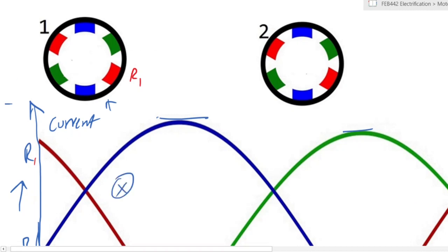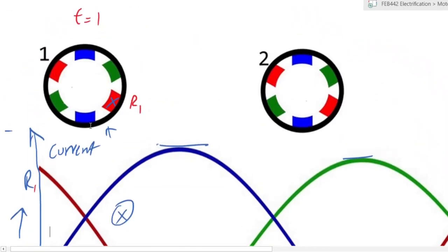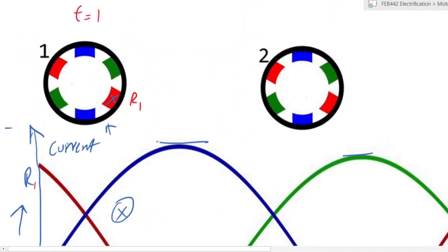It would be into this winding. So it is an X over there. Okay. Blue is at 0 at this time. So there's no current flowing through at this particular instant. And yellow, because it is in an opposite polarity, would be flowing out of the winding. So red is here, blue is 120 degrees away. Sorry, let me mark them the same.